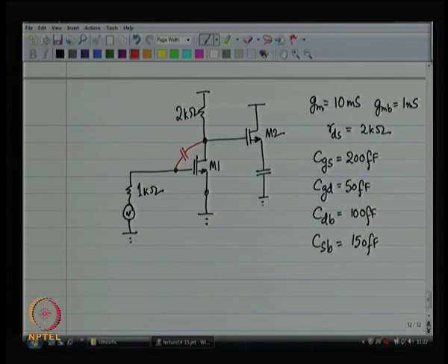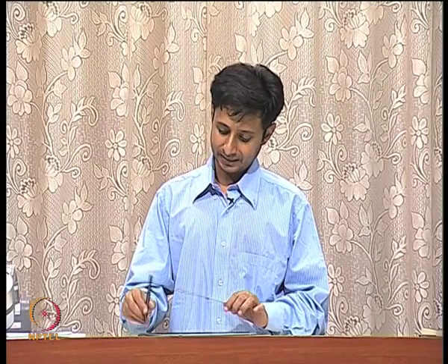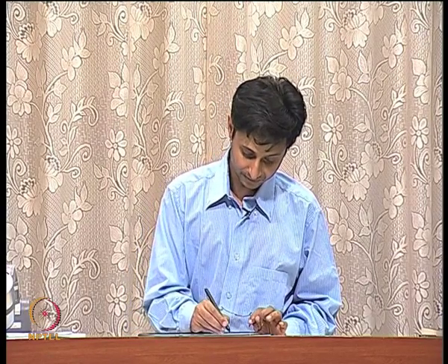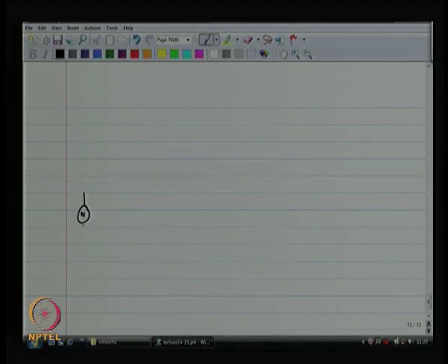So, how do you fix problems with Miller effect? What is the commonly used strategy? You use a cascode, right. A cascode or a common gate structure after the common source structure is what is going to fix the Miller effect problem. So, instead of my second cut design, what I would do is something like this. So, I have my source.